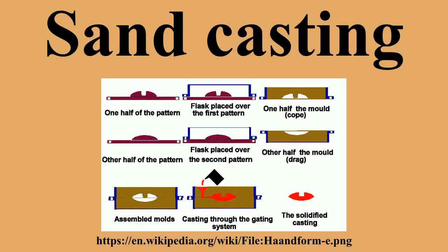There was not one bottleneck to faster casting production, but rather several. Improvements were made in molding speed, molding sand preparation, sand mixing, core manufacturing processes, and the slow metal melting rate in cupola furnaces. In 1912, the sand slinger was invented by the American company Beardsley & Piper. In 1912, the first sand mixer with individually mounted revolving plows was marketed by the Simpson Company.